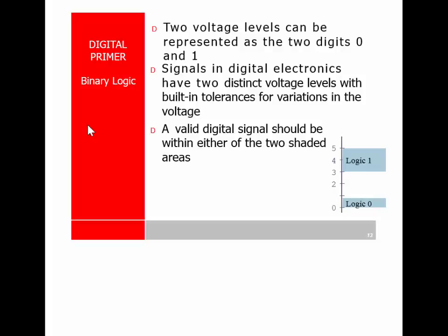It's very common. And if the sensor is an active low, it means that the output of that sensor is going to be 5 volts until a car is there, and then the sensor goes low. So you want to turn on the light when that sensor is low. It's an active low. In other words, a 0 means something's happening. You push a button, and the button will quite often take that.